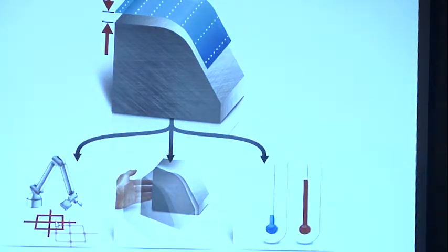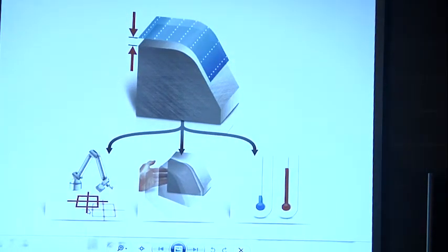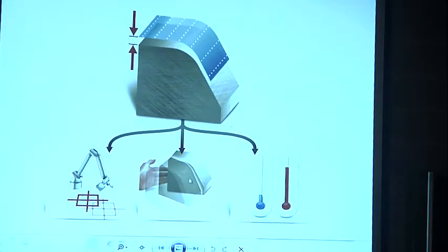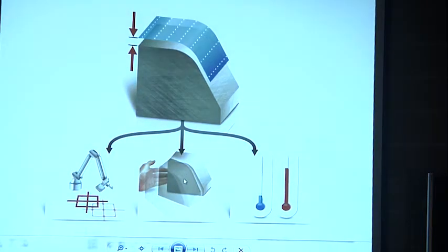Now there are different possibilities to explain why this happened. It might be because the device did move. So let's say you're working on a tripod, someone bumped the tripod, you did not notice it, or you pull on the arm, extend it to the full extent of a joint, and it did move a little bit. Someone might have touched the part. Let's say you go out for lunch, you come back, you try to scan, it's not aligned anymore, so someone might have bumped the part or touched it while you were away.